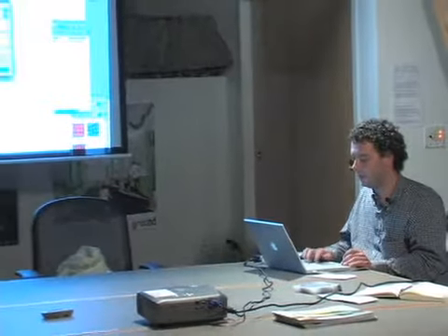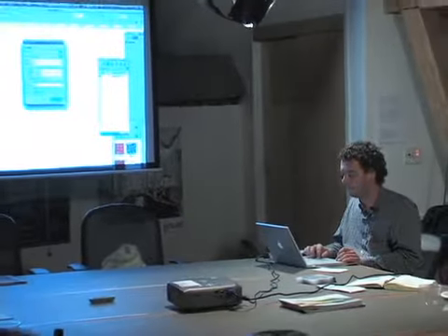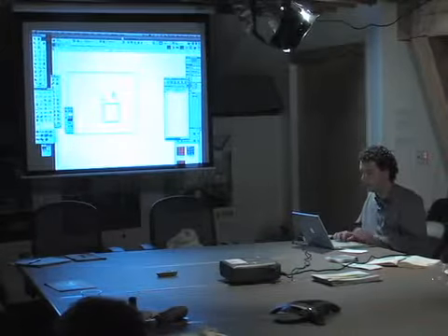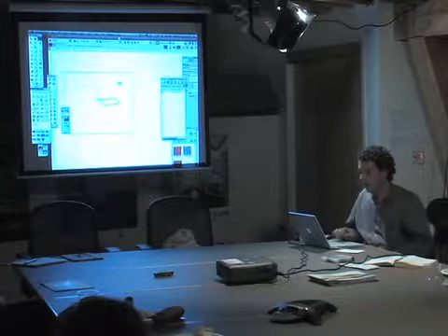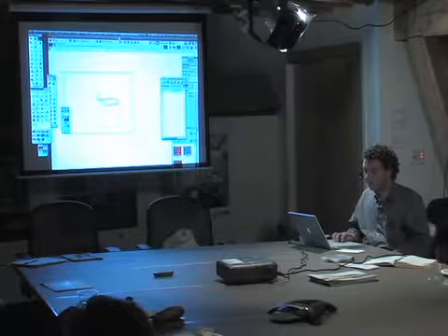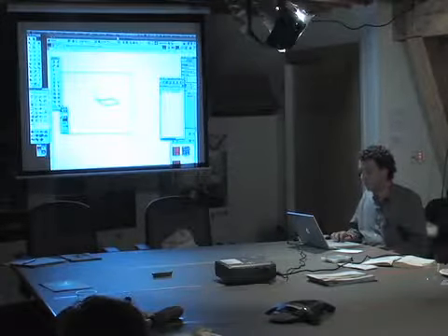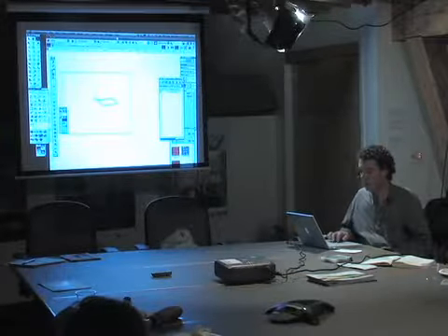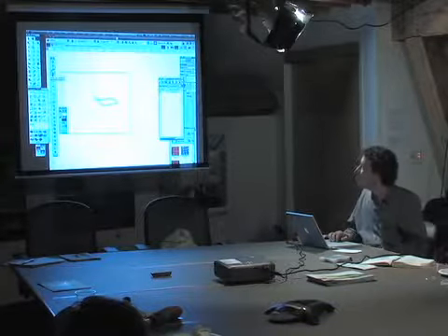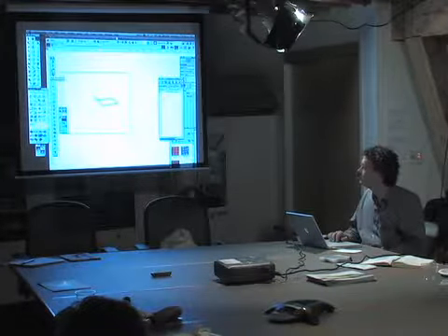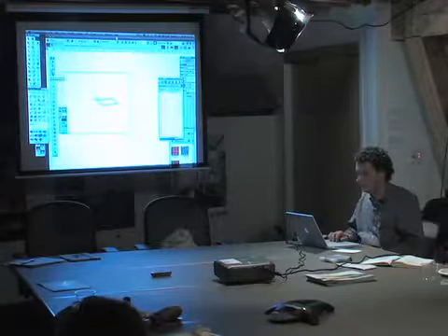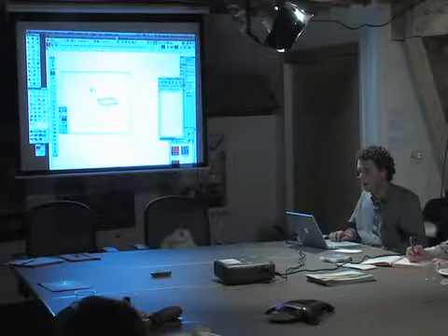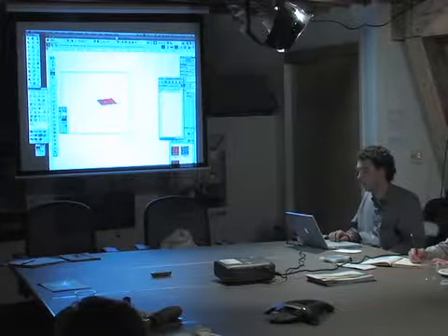Let its position be here at the center. So we just got our rectangle. And now they've had this tool. It was called the protrusion cutout tool. They've renamed it the PushPull tool. Here it's PushPull. You'll be learning this shortcut if you get it: Shift R. The PushPull now begins to allow us to act like we're working in SketchUp.